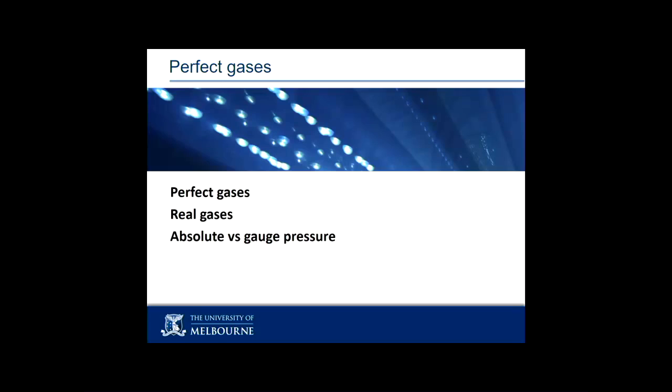So we step on one more round of definitions, and that is the idea of the perfect gas. On Wednesday when I waved my hand at the ideal gas law, so perfect and ideal we use interchangeably for when we're talking about perfect gases or ideal gases. When I waved my hand at the ideal gas law and said we'll use this a lot, that was because half of our world splits into analysing perfect or ideal gases as the working fluid, and half of our world splits into using vapours or boiling liquids as our working fluid, specifically water and steam.